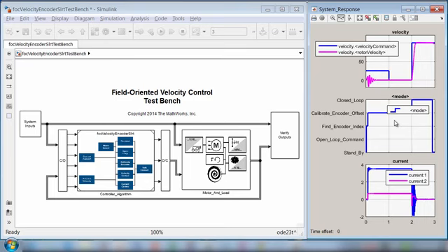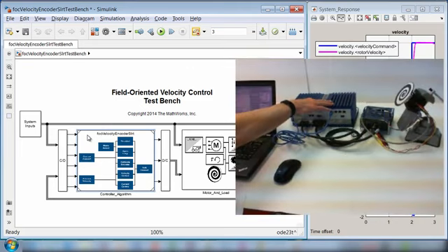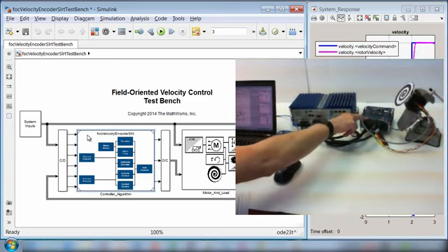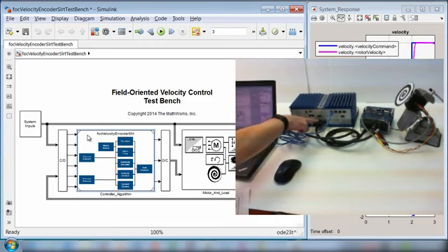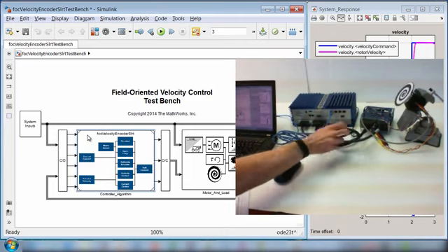Conceptually, I want to take this controller algorithm, which I have here, and get it downloaded onto my real-time computer over here so that I can actually talk to or drive the motor over here and the power electronics. I'm going to do that with some specific I/O cards plugged into my real-time computer and then interconnected between the computer and the inverter with these cables here.